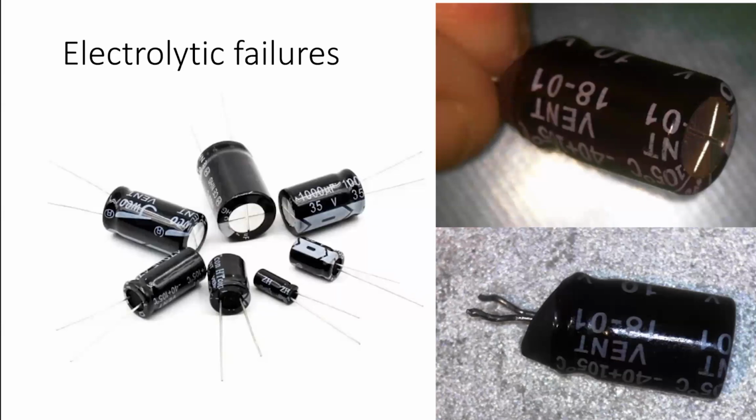There's a catalogue shot of electrolytic capacitors. As you know, these things are voltage sensitive. So there's a minus marking down one side. The minus marking goes to the short lead. The top has got this cross on it to see if it's venting, and there's a rubber plug in the bottom, and that should stay where it is. These are radial components as opposed to axial components. You also get axial ones where a wire comes out either end, but they're very, very less common these days. Any electrolytic capacitor you get is going to be like that.